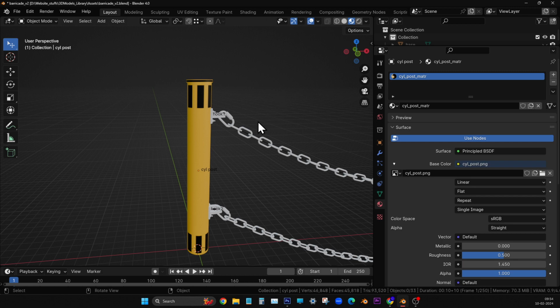Now, yeah, now you have named it as closet material and all. Okay, one thing we have to do, just press dot on the keyboard, right click on the mesh, shade auto smooth. Yeah, that's all. Very good. For this cylinder also you do the same thing. Select the cylinder and shade auto smooth. First cylinder. Okay. Shade auto smooth on. I think for everything we have to do that. Right. Press dot. Okay, fine. Good. Yeah, that's all.